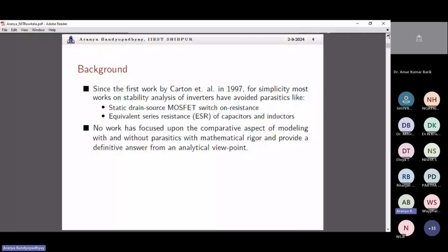And that's why, suppose in your system you have, say, a 50 microfarad capacitor, or let us just say a 47 microfarad capacitor. What will you do? Would you incorporate a direct 47 microfarad capacitor, or would you basically parallel 10 microfarad capacitors? I think you are going to go for the latter option, because especially in the case of electrolytic capacitors, the capacitors often tend to blow up.